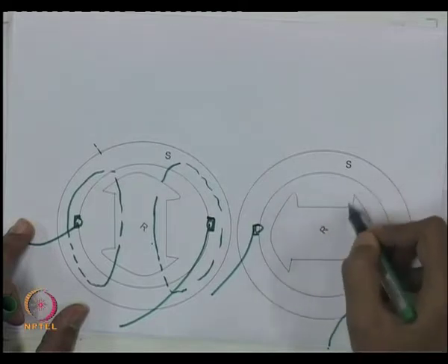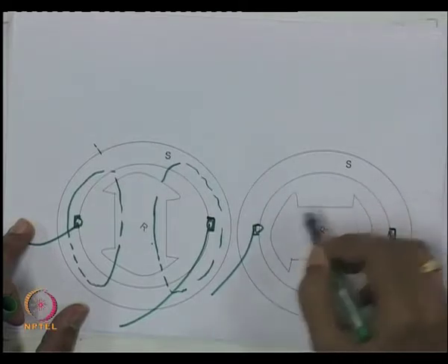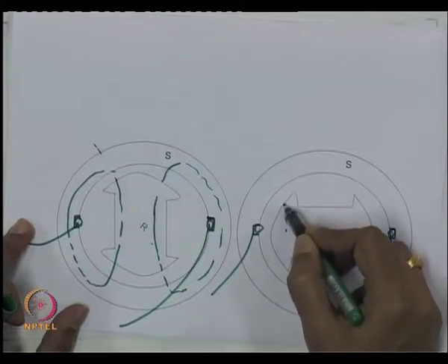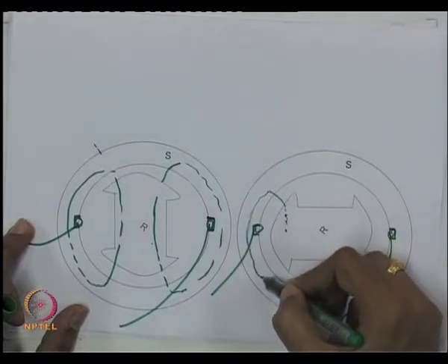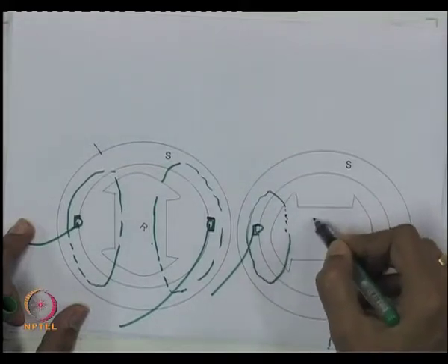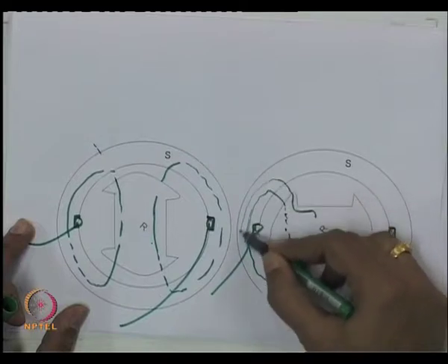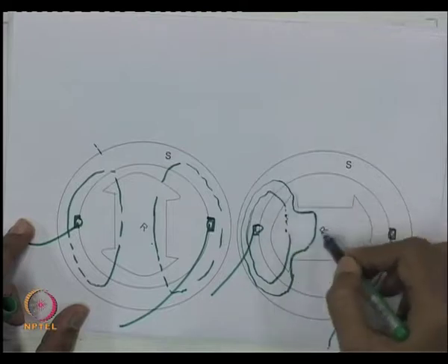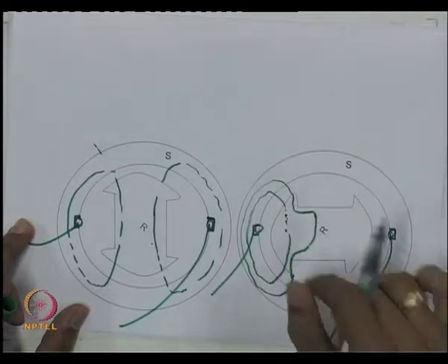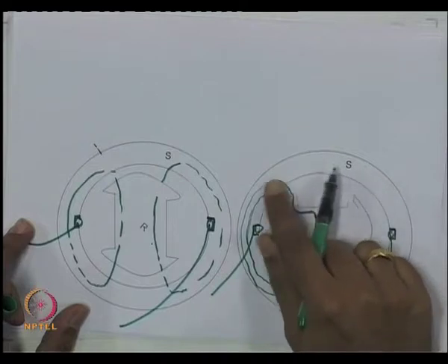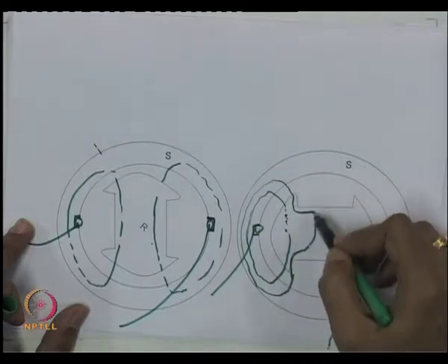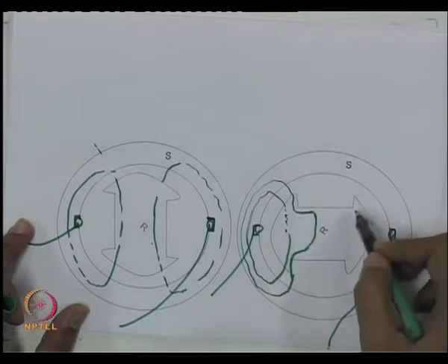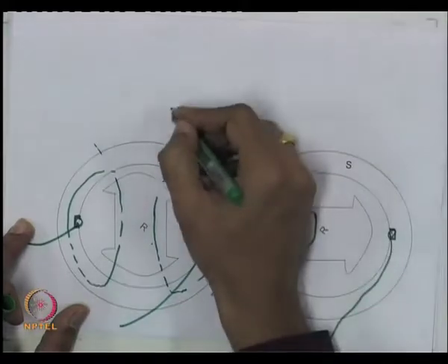This is the air gap. This air gap is more on this axis and less here. So, you will find that there is flux which goes like this, but the flux here will tend to stick to this. Of course, finding the flux path requires a full electromagnetic analysis, but you will notice that the reluctance is likely to be more and the flux created is likely to be less if the rotor is in this position for a salient pole machine.